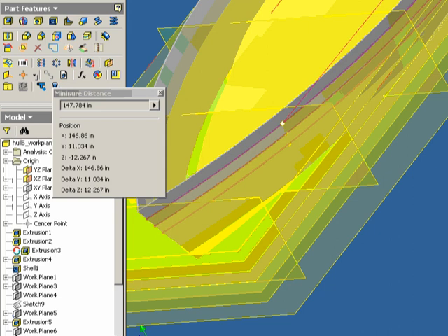That's what I want. This is port side. Even though it says negative 12.267 inches, that's the port side, and you would enter it as positive in the spreadsheet. So this is station area 1, waterline 6. So I would go to my Microsoft Excel spreadsheet, station area 1, waterline 6, and enter negative 12.267 divided by 12.